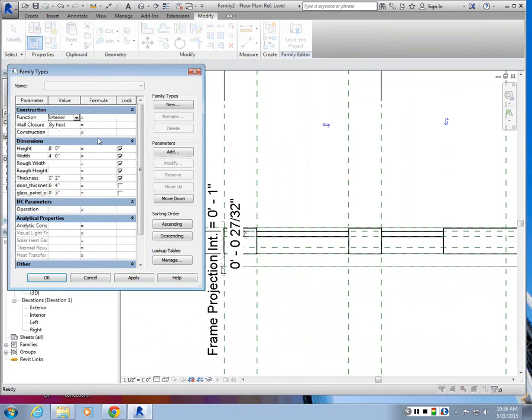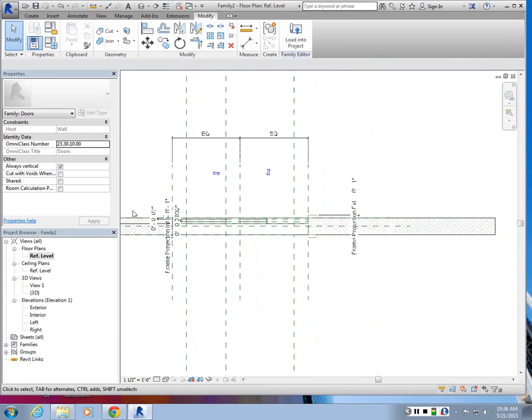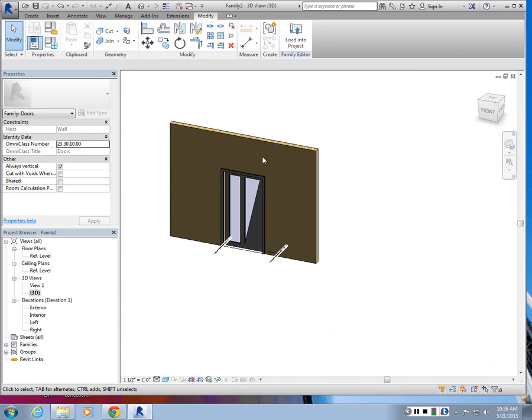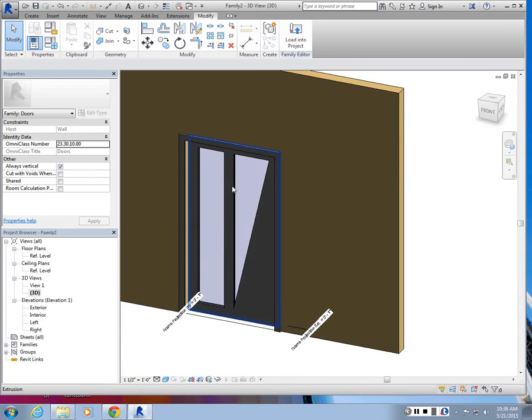So now if I stretch my door thickness, it should keep those dimensions the same. Right? It won't take any effect. So 2 inches. So it's like fixed there. We don't have to have it like parameterized. Yeah, technically, but again, I have to create reference lines, equalize them, and then annotate. So I'm just being practical. Yeah, it's possible.